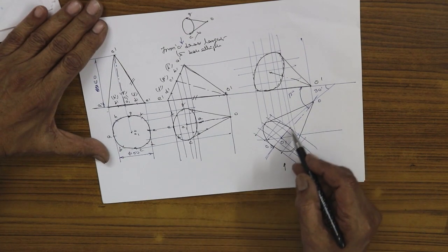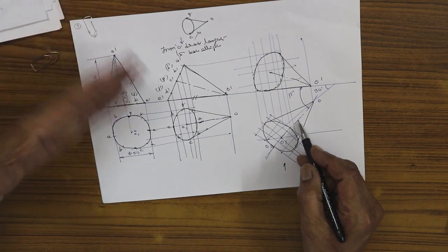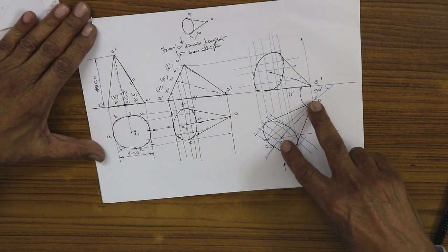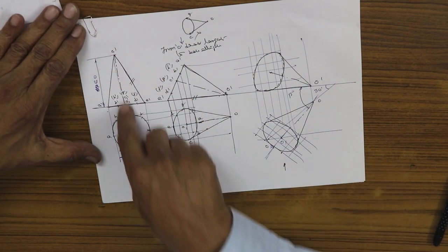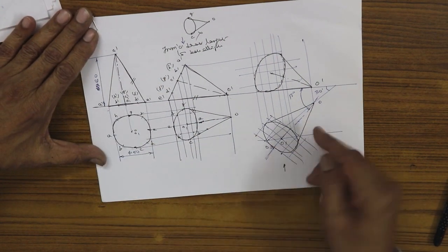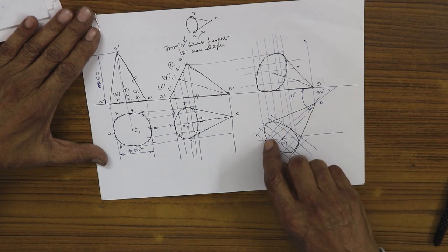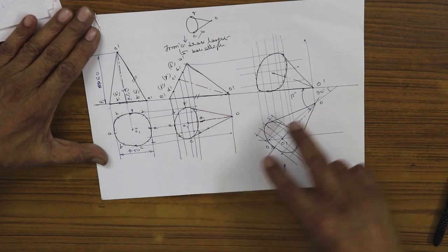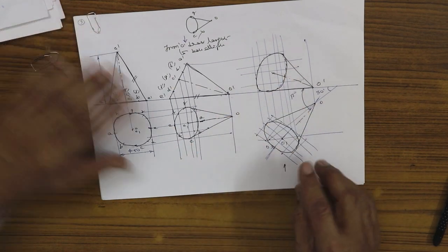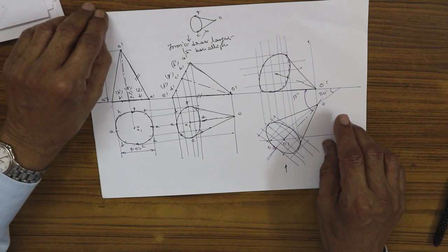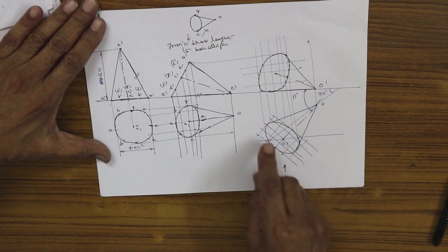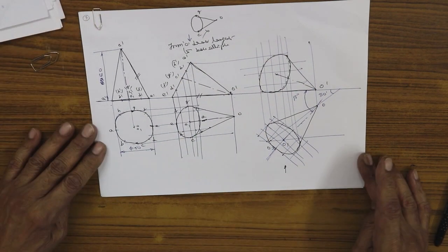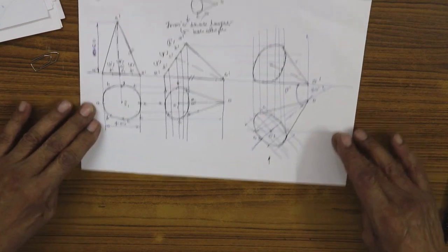So the axis here is inclined. The top view of the axis is inclined at the beta angle. The total true length is given as 60 mm. I did the regular procedure. I had drawn 60 mm, then the locus line, then the apparent length cut, the beta angle, the figure tilted for the beta angle, and projecting it. This requires a small amount of concentration because you have to carry on with the 8-point procedure.